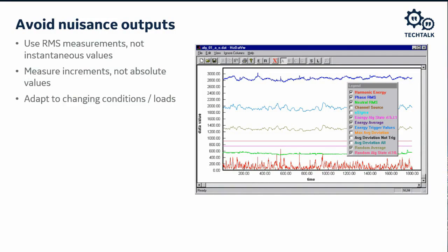Upon power-up, method F learns the feeder ambient harmonic energy level. It determines an ambient average noise level for the odd, even, and non-harmonic energy components of the currents each hour for 3 days. Then it takes the worst average value over this period and uses it as the harmonic noise threshold.